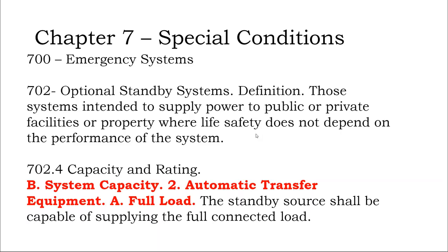So I would caution you in discussion with clients to refrain from calling battery backup systems good for emergencies. Use that word sparingly, because in code it has a very different meaning than what we would think of as emergency power.